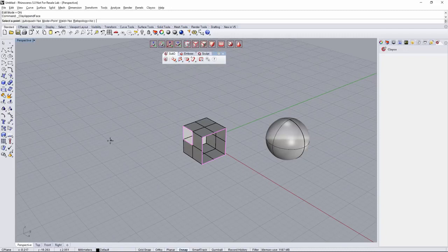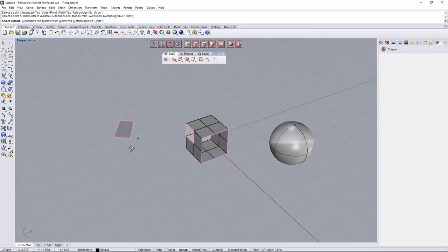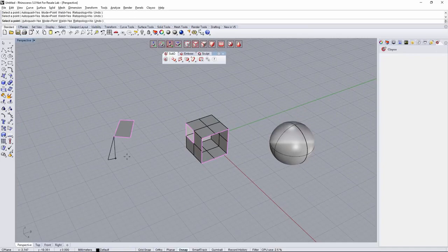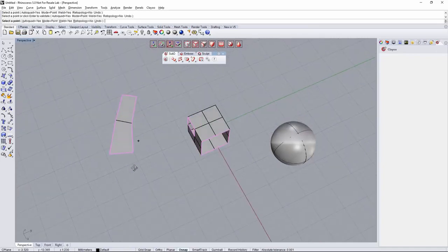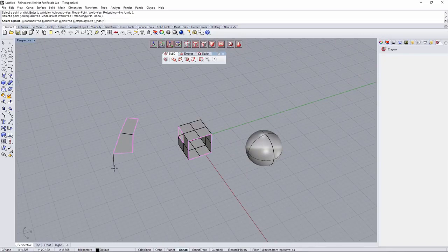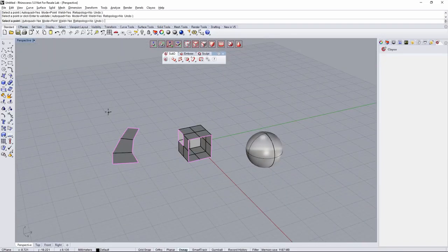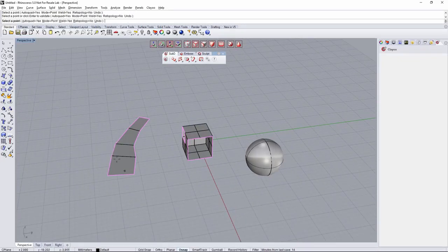We can start from scratch with no geometry selected, and just clicking 4 times, it's gonna create one face. I can just click again 4 more times to create an appended face, and I can do it several times. I have another option, as I see here, it's called AutoQuad Yes. This is gonna mean that when I click the 4th time, it's gonna automatically close the face.